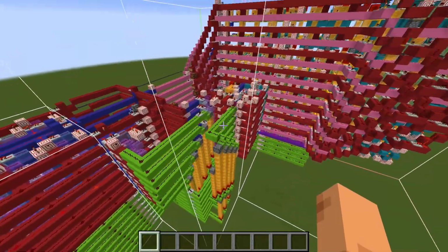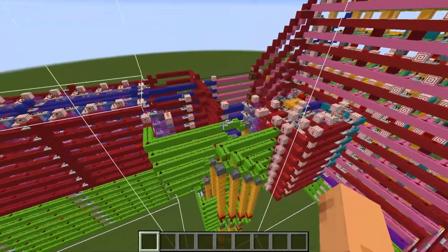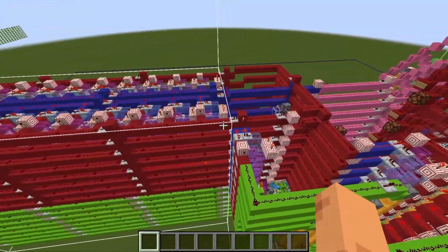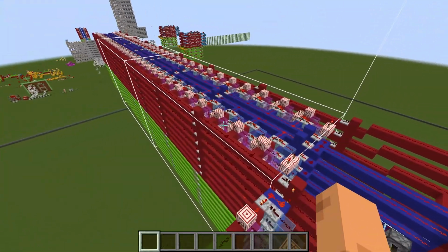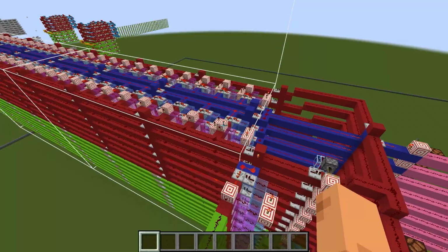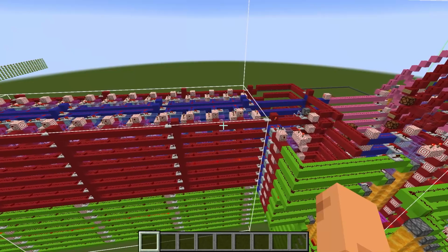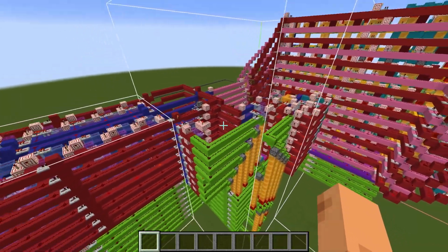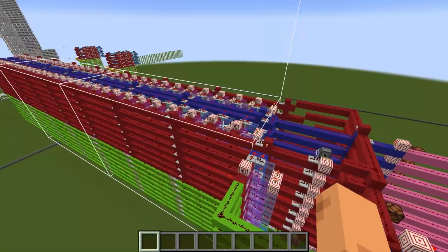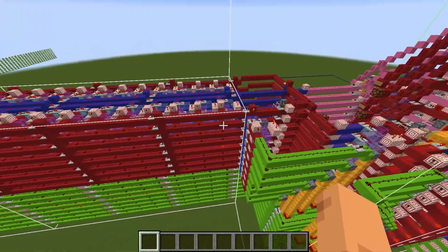So for example, an add instruction can take the accumulator plus the memory address for the second operand to read from, and then it will write back to the accumulator, and so on. So that second data byte is to give the instruction some sort of dynamic input. It can be a literal value, it could be a memory address, it could be anything. So I'll go over the instructions, or a couple of them, for examples, in a bit.